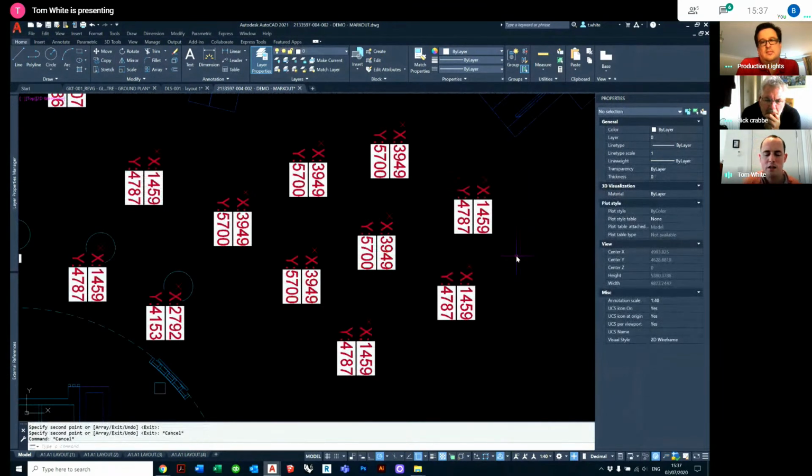So one way to update it, you can type regen, and it goes through the whole drawing and it regenerates, as we talked about. So that's regen or regenerate. And for those who might be involved in markouts, those X, Ys refer to the points. Is that the X and Y readout? Is that something you've done yourself then?